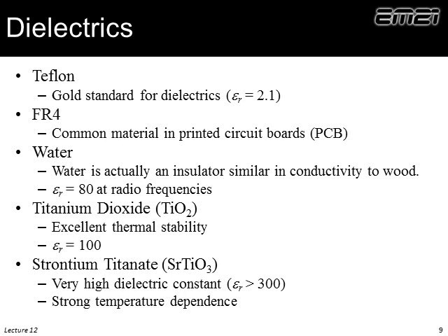Dielectrics, a very common one in electromagnetics is FR4. That's the plastic in a standard circuit board. Teflon tends to be the gold standard for dielectric constants. Anytime you want to calibrate measuring a dielectric constant, we'll put Teflon in there. Make sure we measure 2.1.